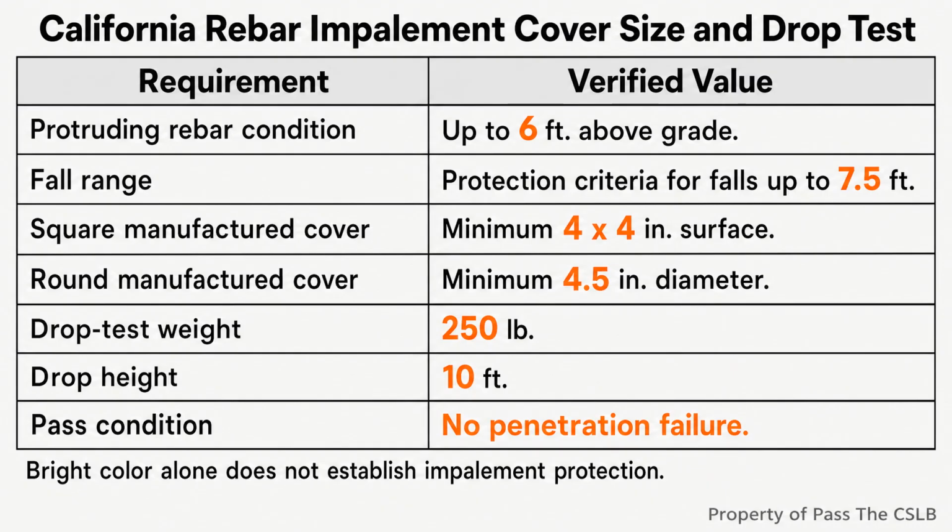Here is the final memory frame. For the contract, think trades. A single concrete trade requires the correct specialty boundary, and framing does not count toward the 2 unrelated trades. For Shotcrete, think live observation. Velocity and angle create the consolidation, so continuous special inspection must be in place during placement.